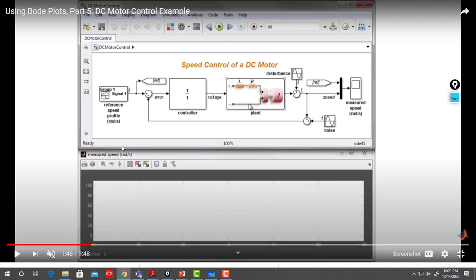so basically you can go with him here. Went to the control system designer app. You have this system, so you can get the transfer function of it, and then draw in here the reference and the desired. This is the desired reference and this is the output. So it is for a feedback controller of 1.